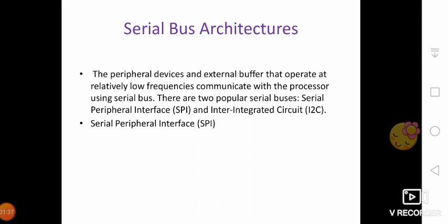Typical applications include secure digital cards and liquid crystal displays. SPI devices communicate in full duplex mode using a master-slave architecture with a single master. The master device originates the frame for reading and writing multiple slaves. Slave devices are supported through selection with individual slave select, sometimes called chip select.